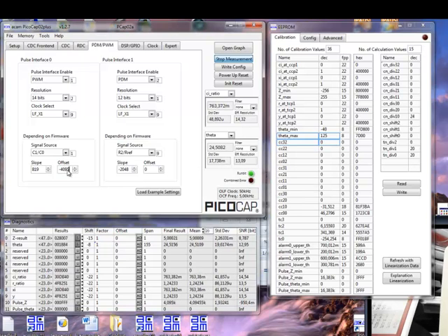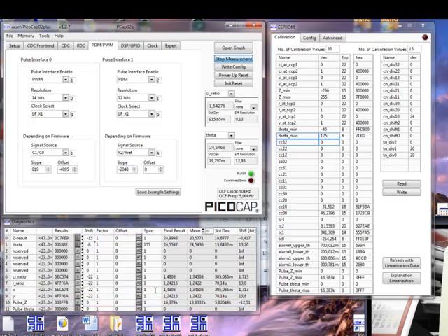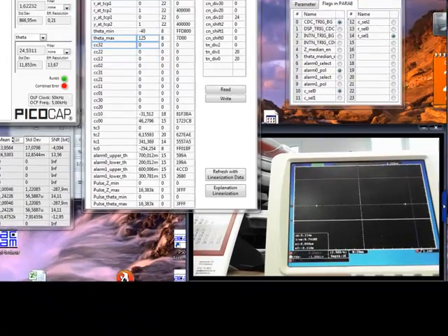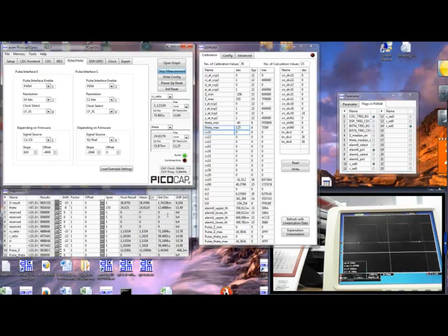Now if I do that with a minus sign, you already see here on the output that it now goes to low because I'm in the lower range of the sensor. I now switch to the higher limit, and you see the output is already between 0 and 1, and if I go to a value in between of that, I get the expected output, which is here roughly like 70-30% duty cycle. Basically, we have the PWM output as desired already.